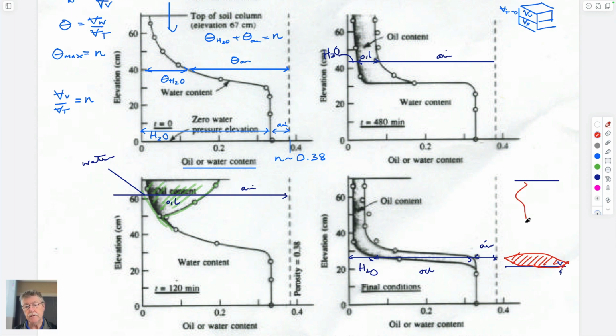And I guess it would be stuff here. And I need a blunt object to represent that. That would be this. It's not very blunt. And so if you think about going down through this particular zone, I guess this here, then this capillary pressure curve is really, with elevation or with capillary pressure, this is defining what those saturations are, or volumetric moisture contents, right?